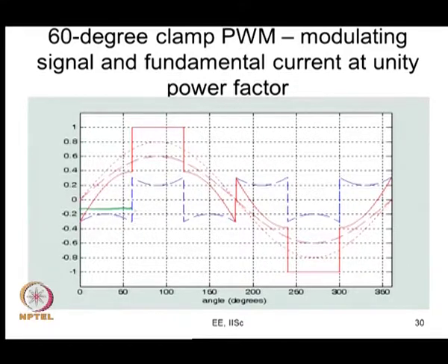One would expect this to continue here, the same minus V error, but this is a discontinuous PWM and the R phase is clamped here, and therefore it has no error voltage here. The error voltage is 0. This is between 60 and 120 degree. Now you go between 120 and 180 degree. What happens? The phase comes out of clamping and the current is positive, and therefore you will have your error voltage like this. This is what it will be.